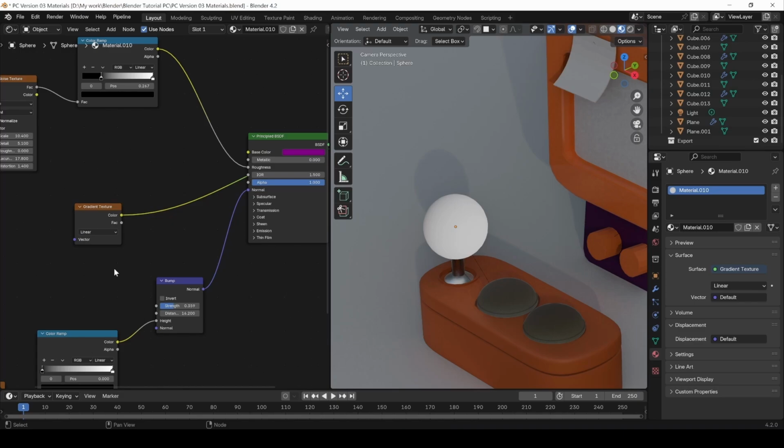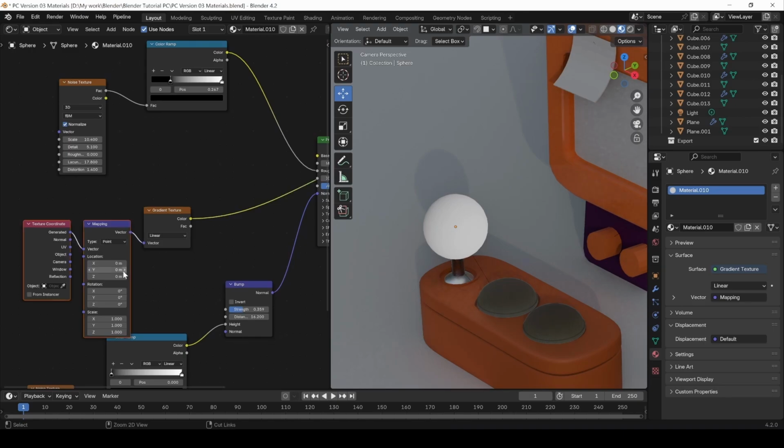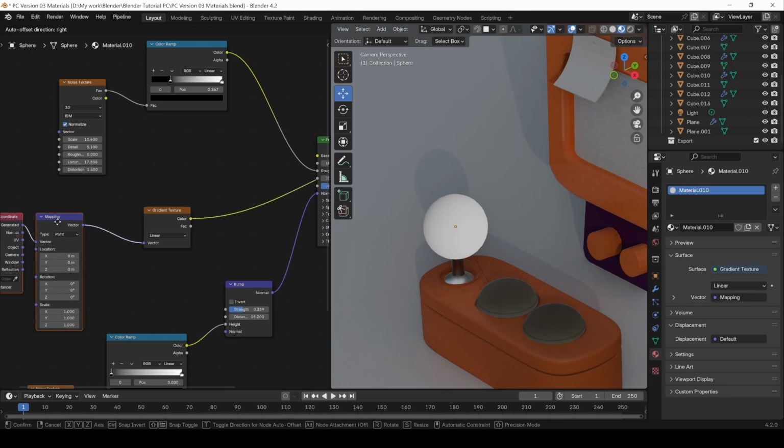As we said before, to know where to put a texture, Blender needs the UVs. And you need to specify on what UVs, like what part of the UVs is gradient black and what part is gradient white, for example. Because Blender does not know, it does not show anything to you correctly. So, how to fix that? Click on it, then Control T. You will have these nodes.